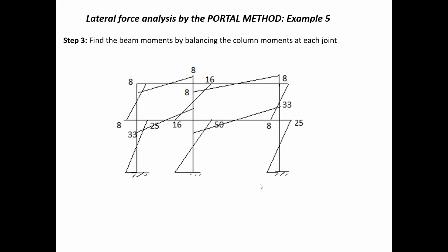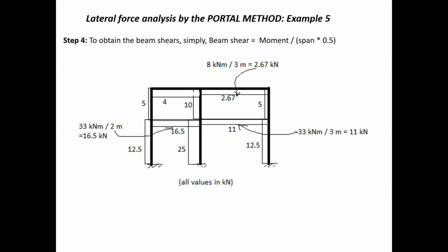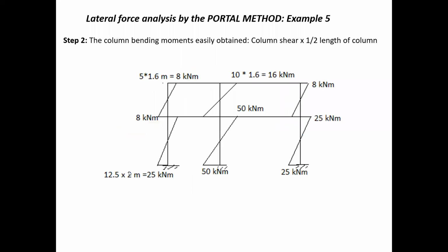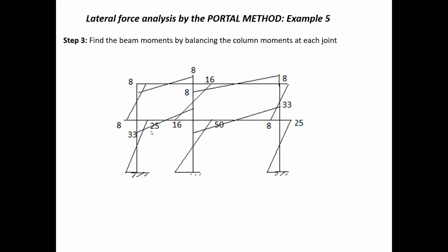Now to find your shear forces, okay, the shear force is very easy. You just get the reaction at each end. Now what's the reaction at each end? You just get the total moment, this plus this, 2 times the moment at one end, divided by the length. Very easy, right? So this would be what you got, 25 times, what's the length? 25 times 4, 100. Okay, 100 divided by 4.